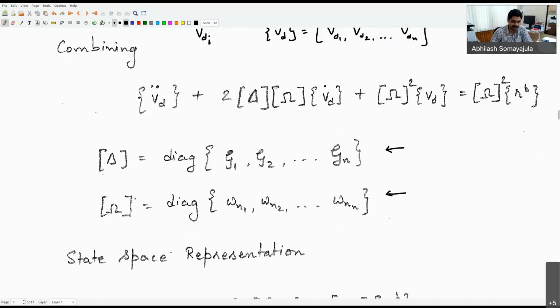Now one might argue, why not have this matrix as a full matrix, so I can tune more, I have more parameters to play with. But for typical control operations, it makes sense to look at the damping modes individually, because we want to look at each of them individually and then combine them together. Yes, you could put a coupled damping also as a part of the process, but usually the coupling is not quite strong, or at least when we are interested in the guidance system, we are not really worried about the coupling here. So it makes sense to tune it.